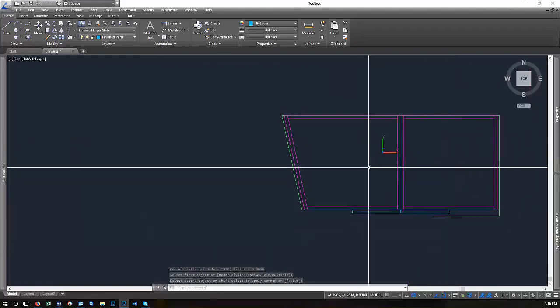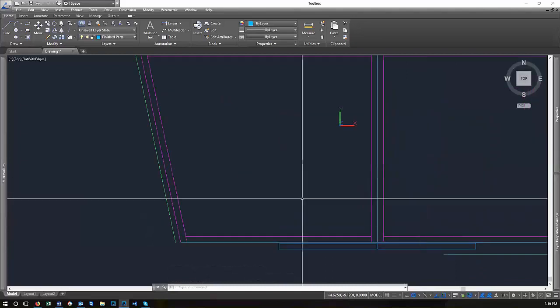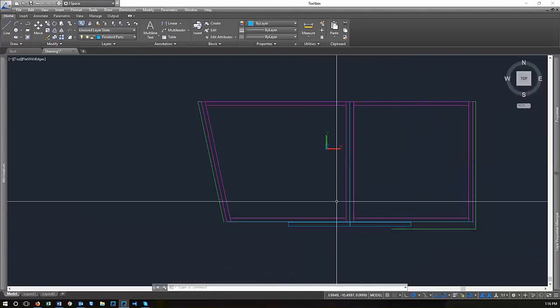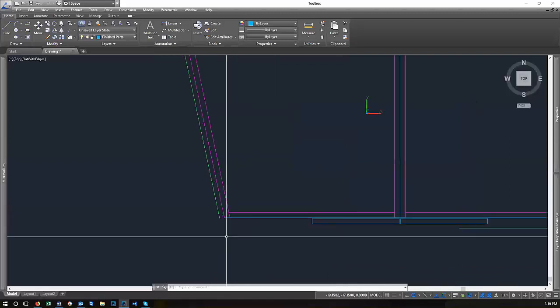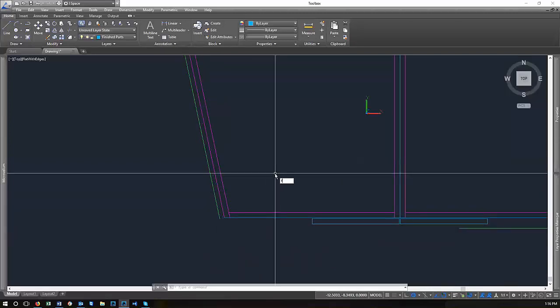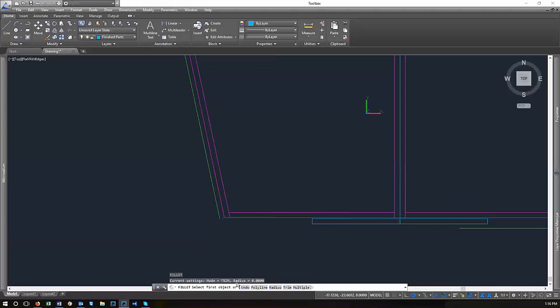So let's imagine these are just the only 2 cabinets that are coming on this countertop, and we want to put a radius corner on here. Fillet is also the command for that. So fillet, you can then add a radius. So let's do something nice to keep from hurting people. 1.5. So I'm going to put a 1.5 radius on this corner between that line and that line.